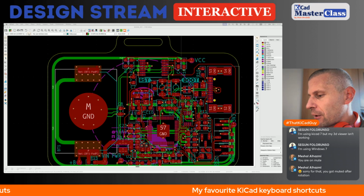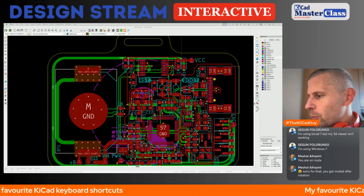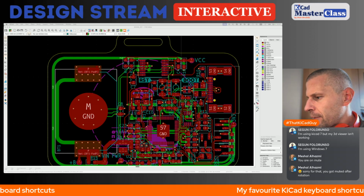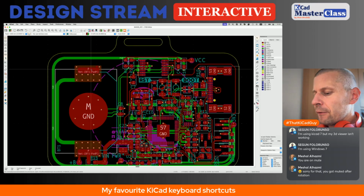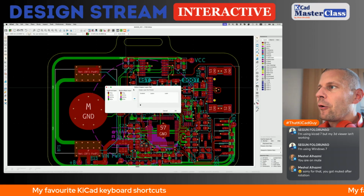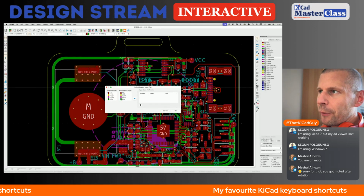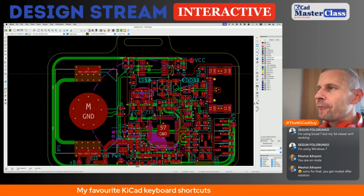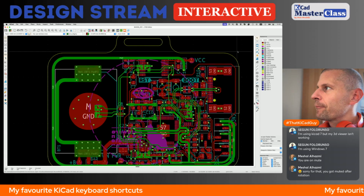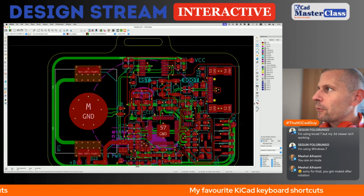Back to shortcuts. Let me go through my notes. Toggle layer. It's V. There is a dialog, Copper layer pair. By default, it is front, top and bottom. And when pressing V, like victory, you can see here in the layer selector, you are switching between